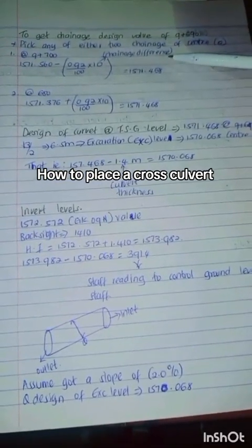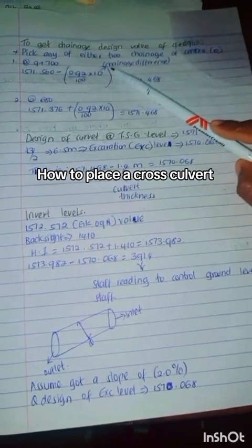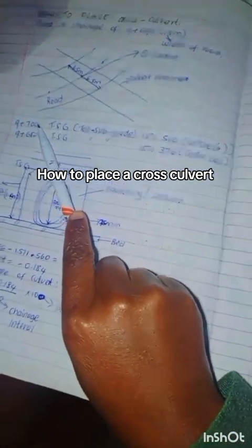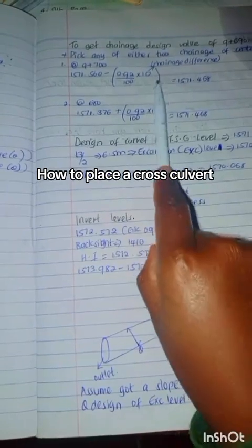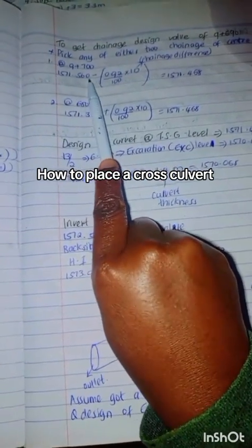The next thing you need to know is how to get the chainage design value of 690. You pick any of the two center chainages, 9 plus 700 or 9 plus 680, to calculate; both give the same value. Using 9 plus 700, the center design is 1571.560.